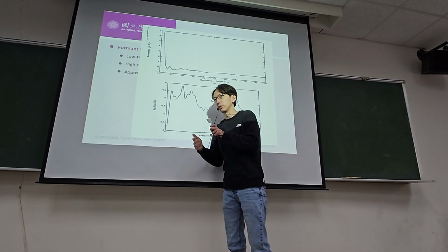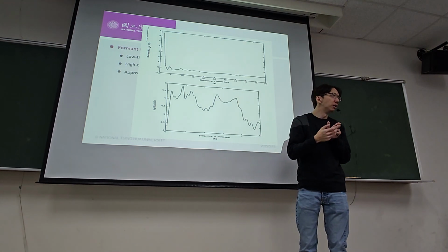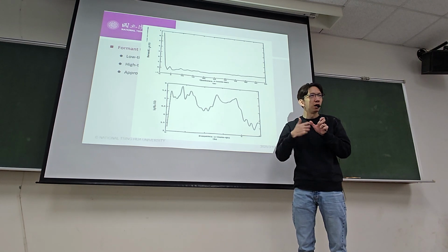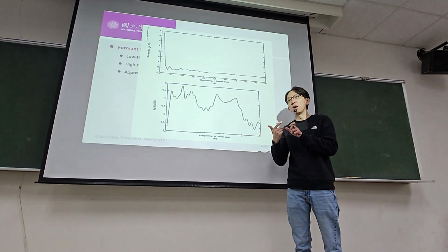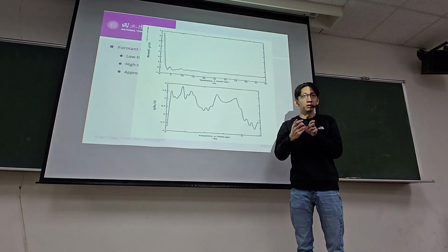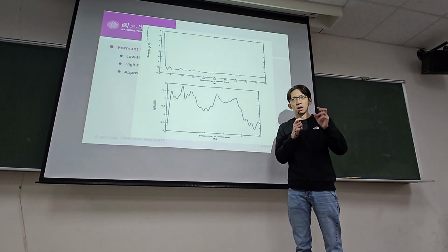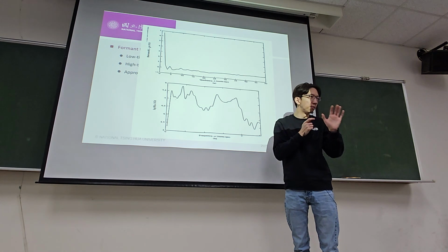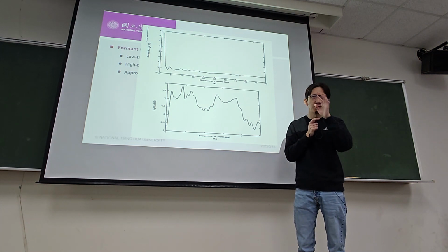So again, cepstrum analysis is a smart way of disentangling source and filter. The idea is a hypothesis of a source exciting a filter. Again, I want to point this out: this source and filter model of speech production is hypothesized.